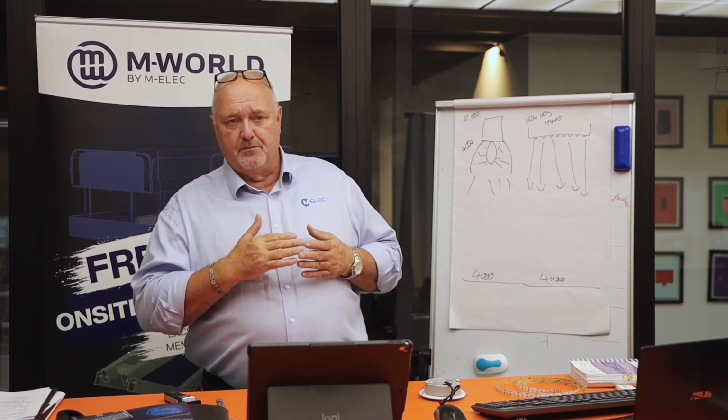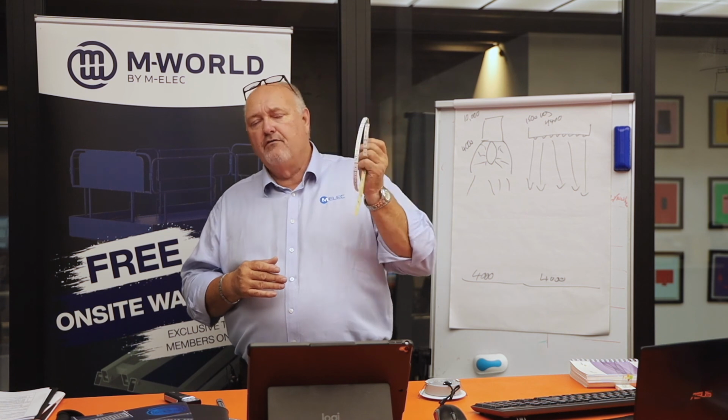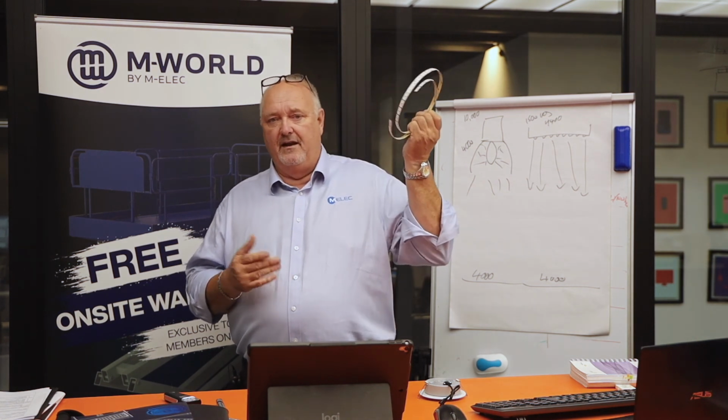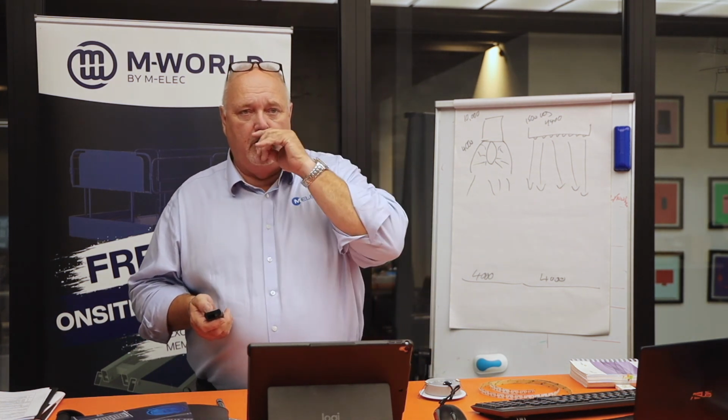And that goes down the line. So you've got to pick the rating that is the most suitable for what you're doing. If it was an LED strip and they said it's IP68, I really wouldn't have any concerns putting a jet of water on it, because it's going to be completely sealed. It's going to have resin, and the resin will be able to handle it as well. Okay, so let's move on. And then we've got the old IK rating chart just off to the right there as well.